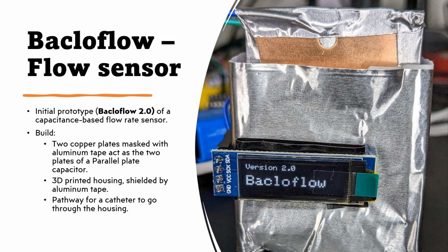There is a housing that houses both capacitive plates, and there's a hole for the catheter to pass through, and that is how the capacitance is measured. Whenever fluid flows through the catheter, the dielectric between these two plates changes slightly, and this small change is then quantified as a change in the flow rate.